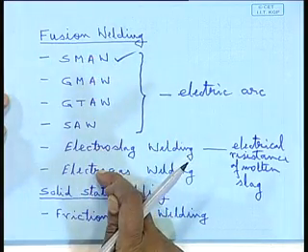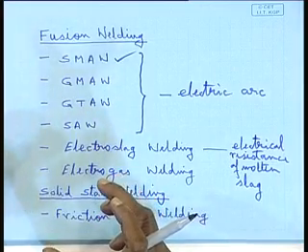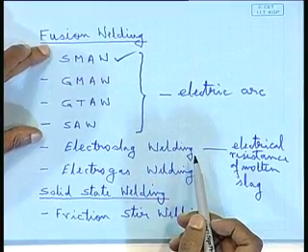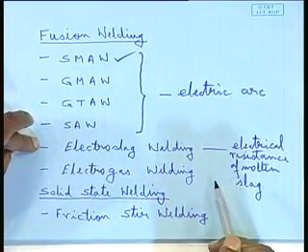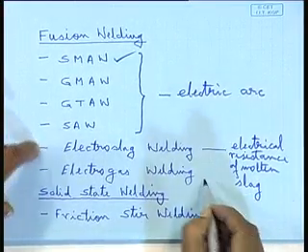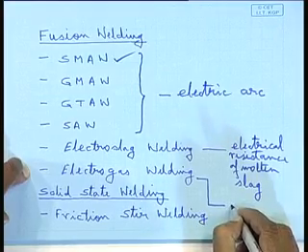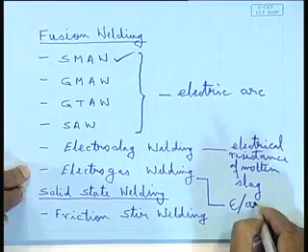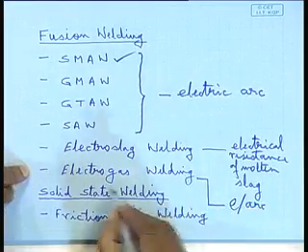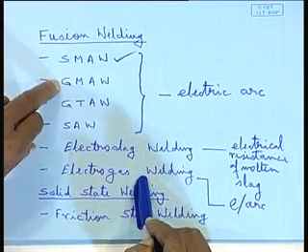because all these are fusion welding processes. So there you need to have some heat generated which will melt the metal as well as the electrode, right. So in the first 4, the heat is generated from an electric arc. In this electro slag welding, it is generated from the molten slag, right. Again, electro gas is from an electric arc, right. Here essentially a gas shielding is there. We will see later how it is different from gas metal arc welding.